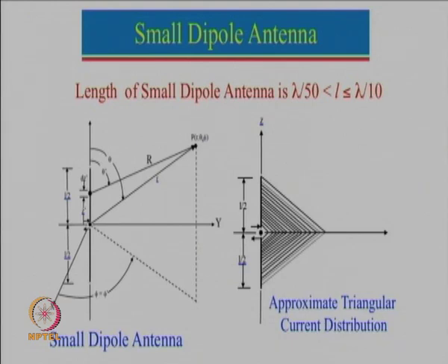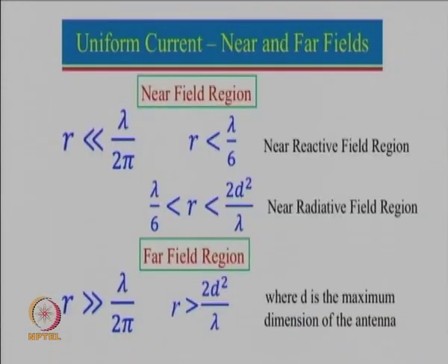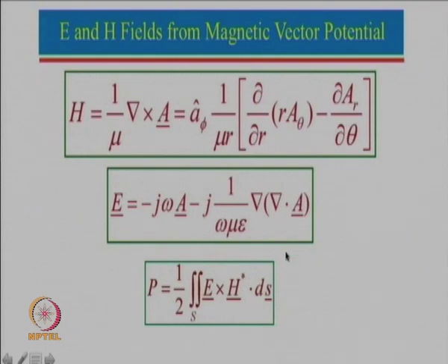So, power radiated can be found by using this particular expression here, and since there is only one component now, E cross H conjugate will be replaced by magnitude of E square divided by eta, because H is nothing but E divided by eta, which is 120 pi. So, by using this we can find what the power is, because we know the E and H fields, and then power is now given by half I 0 square times R r.